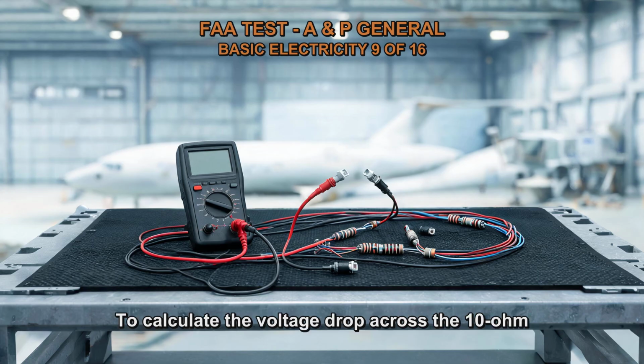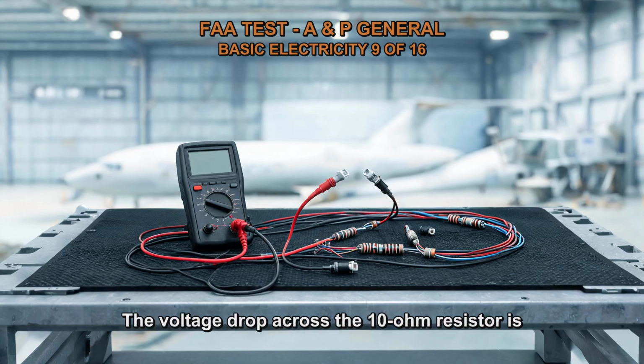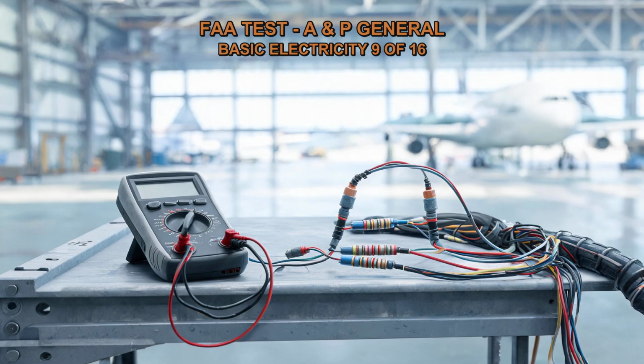To calculate the voltage drop across the 10-ohm resistor, use Ohm's law. Current through the series circuit is I equals V divided by R1 plus R2 equals 30 divided by 10 plus 20 equals 1 ampere. The voltage drop across the 10-ohm resistor is V1 equals I multiplied by R1 equals 1 multiplied by 10 equals 10 volts.